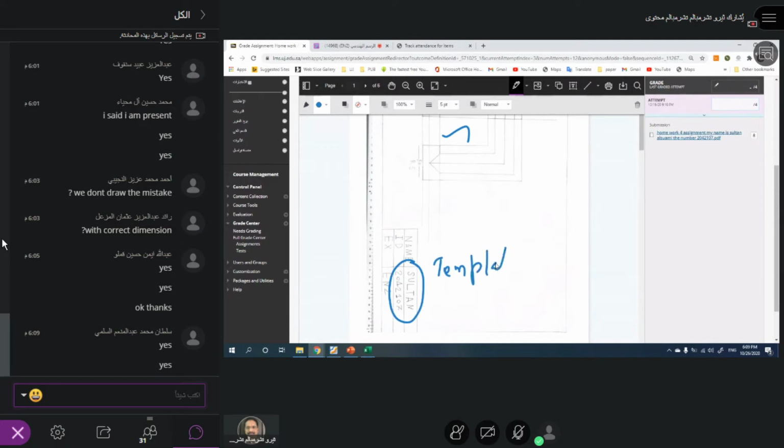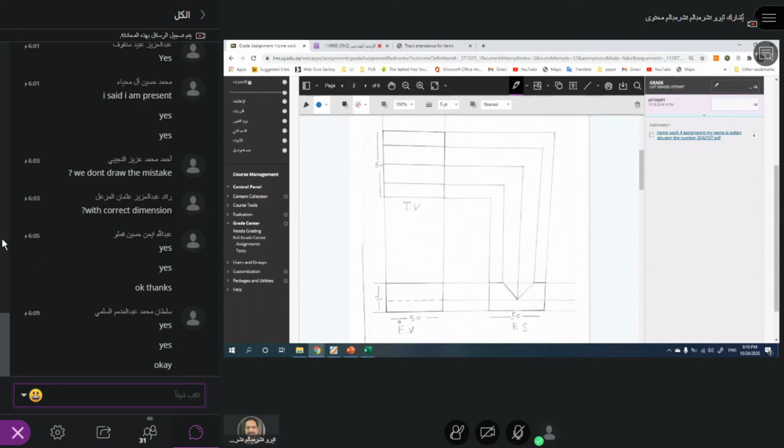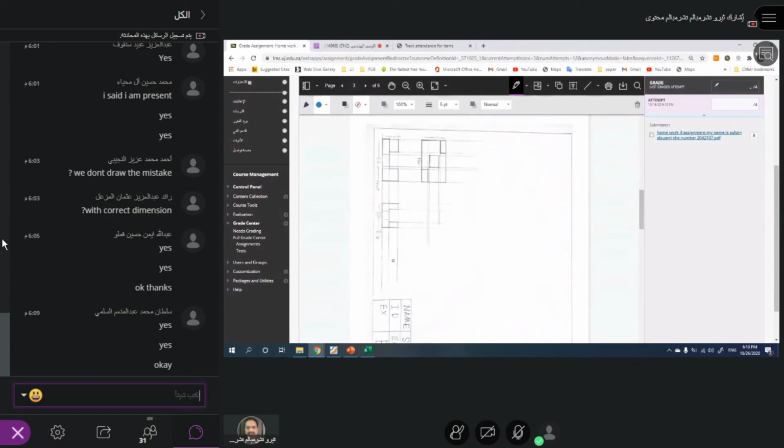Okay, next time you improve it. Okay, use the 45-degree angle here. Right. And hidden line is okay. Show the lines. This is a thin line. This will be thick line. So you can show clearly which is the component, which is the extension line. All right. This is okay.